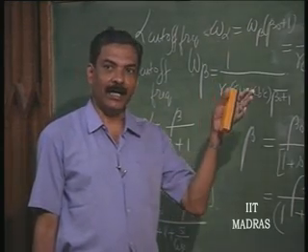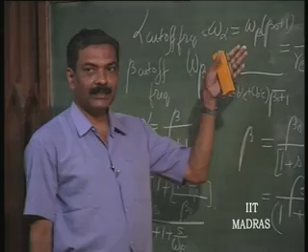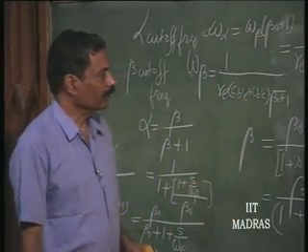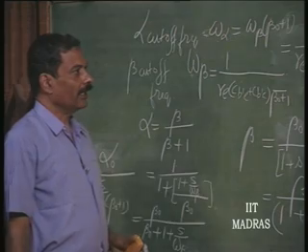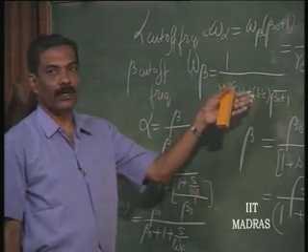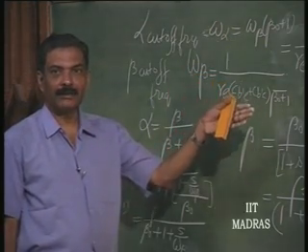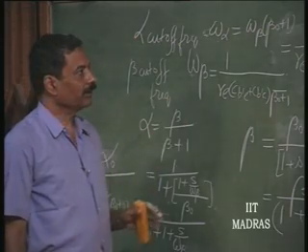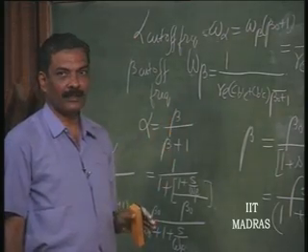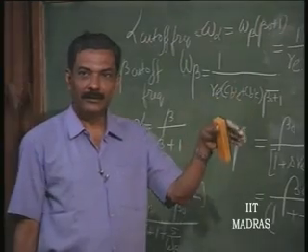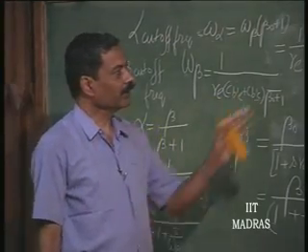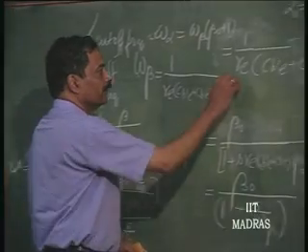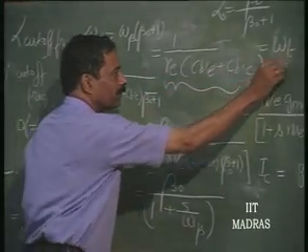That is beta, if you consider, beta itself is going to fall to a magnitude which is less than 1. Okay. And or alpha becomes 0.707 times alpha naught. So, it is the upper cutoff frequency of alpha, or where beta falls to less than 1, that is the transition frequency, and this is a parameter which is given by the manufacturer.